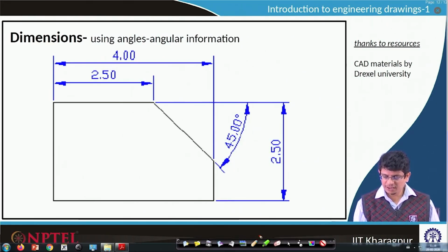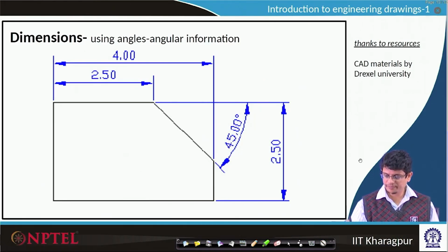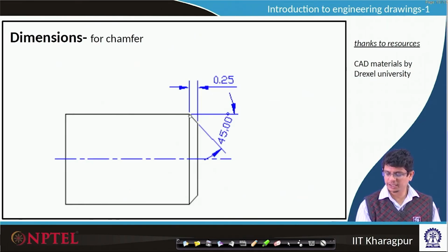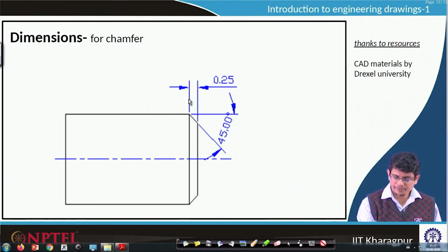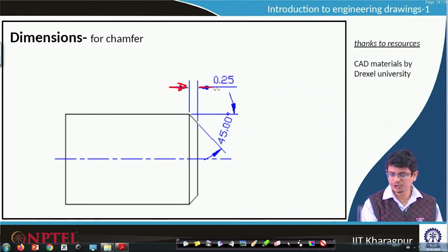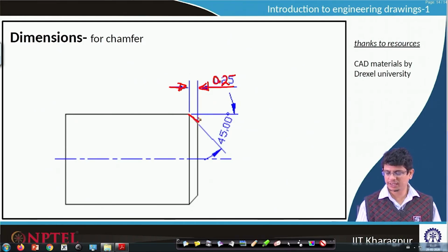If it is angular information, we usually represent it in terms of angles. Any chamfers we represent including the chamfering lengths, using these continuous lines. Note that the dimension is outside because the gap is too small. So, it is not a good idea to show it in this way, this is wrong. It facilitates us to show these small dimensions from outside. And also there is chamfering for this machining process, which will be a 45 degrees angle.